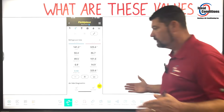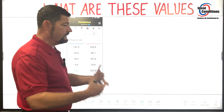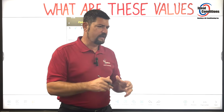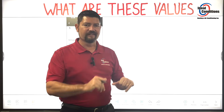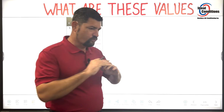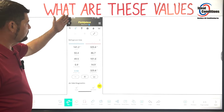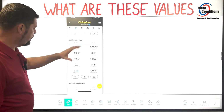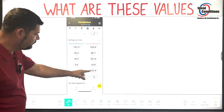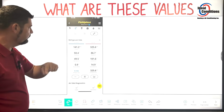Let's look at some situations that are data that we've taken out of the field, and now let's put you in a real live situation. Let's get out of the simulator that we were just in, and let's look at real live data. We have things time-stamped. We're using software here. We know what type of refrigerant. We have 410A. The discharge pressure is 325. The suction pressure is 141.